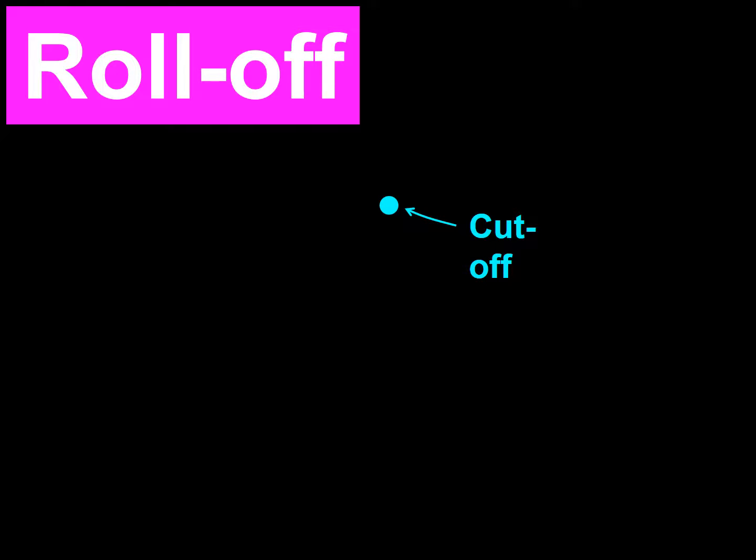I refer to it as the pivotal point in addition to being an important point to understand filters because it serves as a fulcrum for the roll-off. I like to think of the roll-off as a line pivoting at the cutoff point, as I have shown in this frame.